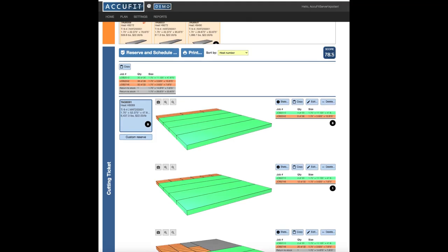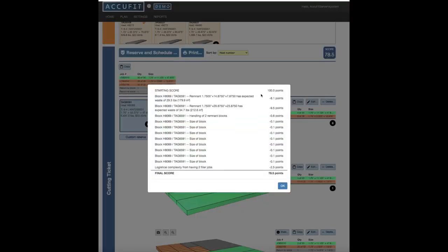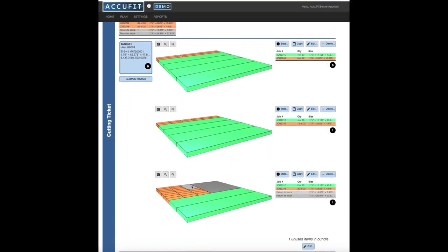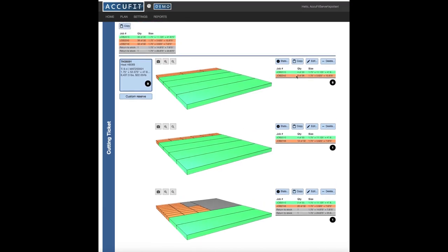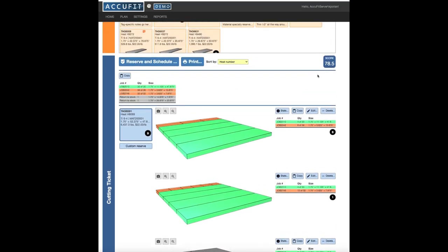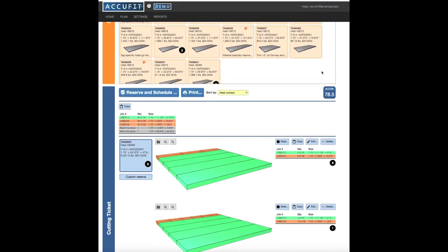And the result of this on a score is that there's no scrap, but there is 64 pounds of expected waste based on the remnants that are left over. These 2 remnants, you have 29 pounds and 34 pounds that are left from these 3 pieces of plate. That's this gray area, and that's roughly 112.7 pounds. The amount of expected waste is worth about $1,280. And so we just reduced from a $3,534 loss to a $1,280 loss. So that's a better result.